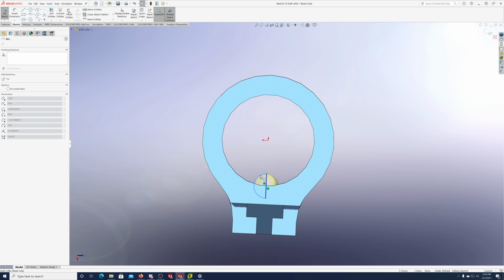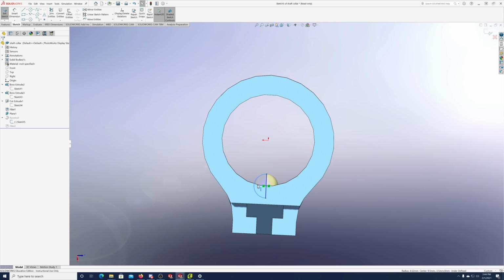Okay, so one thing is when you grab things and drag them around, you can see by how they're moving, you can tell what's not defined. So you know that, for instance, the length of this line isn't defined. So let's undo so it's the size you wanted it. But then let's give that line a dimension. And it's 5.